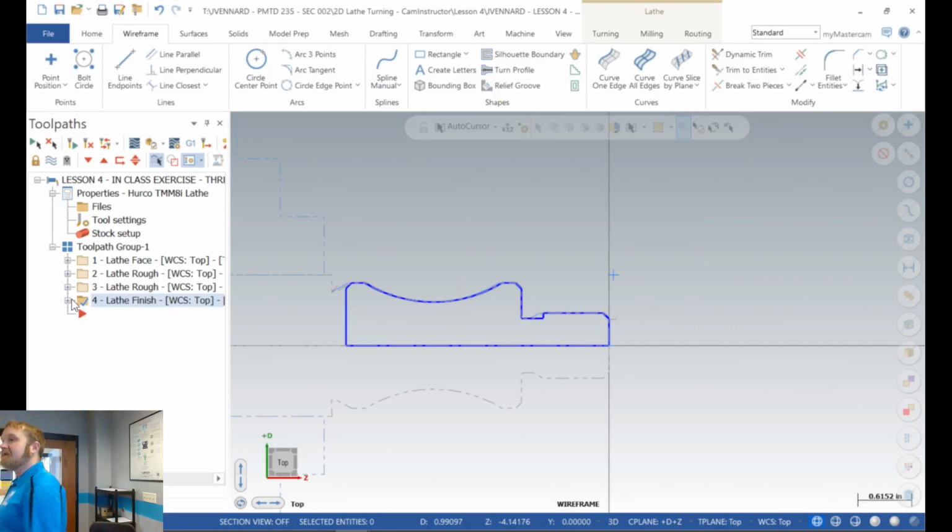And here's why. Because I'm going to use the same tool, and this is the way I think about stuff on the CNC. Does this have to be there before I do this? And if I can eliminate a tool change, I don't care if it's the mill or the lathe, I'm going to eliminate 10 to 15 seconds out of that program. If my rapids are turned down, that could be 30 seconds on some machines. Some machines have slow tool change.